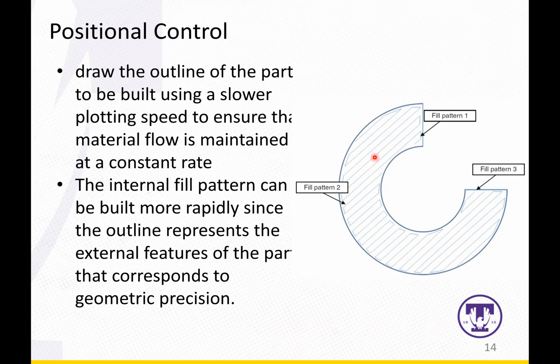When the printing is done, all the infill is inside the three-dimensional object. So when printing the infill, usually the nozzle will move more rapidly to gain some efficiency, and obviously you don't need as precise features as the outer lines. So that's why you could gain some efficiency by speeding up the infill printing.